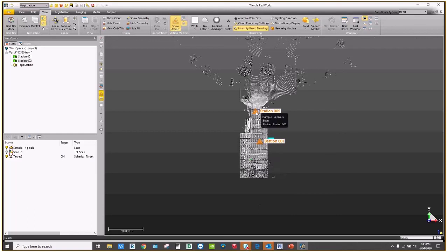And then station 2, I just backsighted that and scanned. I didn't have another foresight out, but I could have. And we could just keep going like that, leapfrogging along. So that's another way of doing it, depending on the options available to you out in the field.